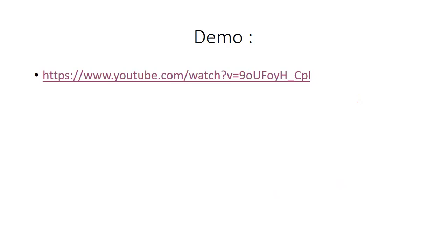And let me have these construction lines, and the thickness of construction lines is 0.13. Then make use of the move command and move this ellipse to the bottom portion from here to here with the move copy on, and the thickness of the ellipse is supposed to be 0.5 millimeter on either side. So now let me change the ellipse thickness to 0.5 millimeter, and then using a line command with a thickness of 0.5 millimeter, one can draw the cylinder